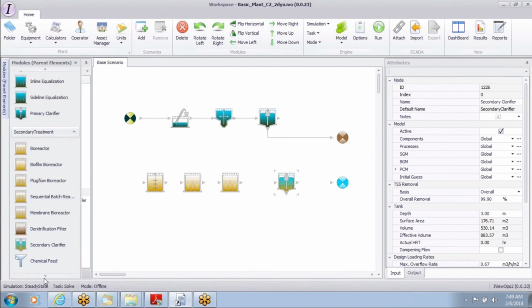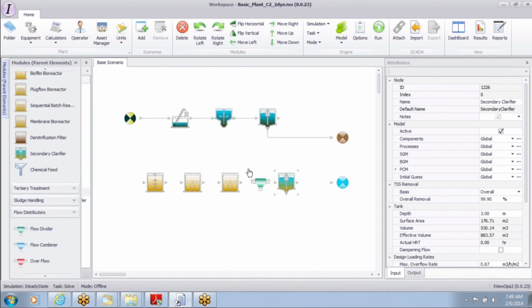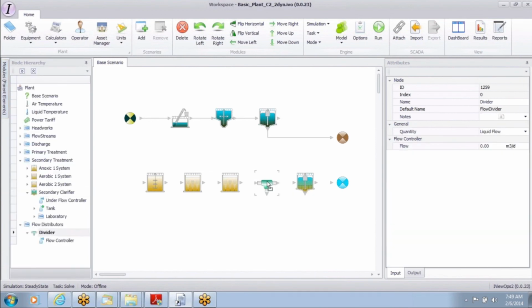So let's go in here and look for how I put in the nitrate recycle. Again, all of this is in chapter 2 of user manual part 1, A or B. So here's a nitrate recycle. So I went into the flow splitter, the green one is the nitrate recycle. Now let's say, okay, one thing about convention is that the main flow is going to flow through this. What is pumped out or what is split out is going to come out from this bottom of the tube. Let's say I want to flip it so that I can put this thing properly on my GUI. Let's say I use flip horizontal and that turns it around. This nitrate recycle is going to go in here and come back in here.